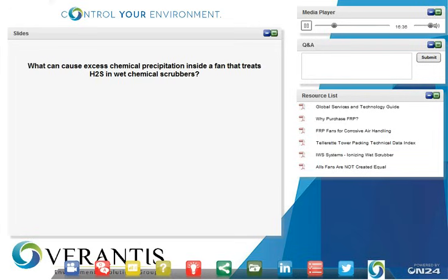We have another question as well. Can dry glass or exposed fibers simply be wet down again by applying new resin? Now, this is Junior Hardman. No, it cannot, because the biggest problem you're going to end up with is you have chemicals already in the glass and potentially on the resin, and you're not going to get good secondary bonding, and eventually it's going to peel right back off. Okay, move back on.